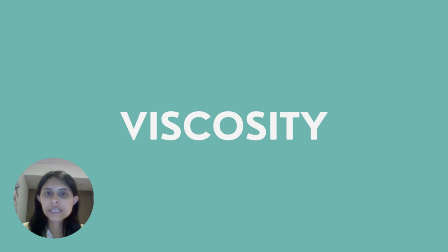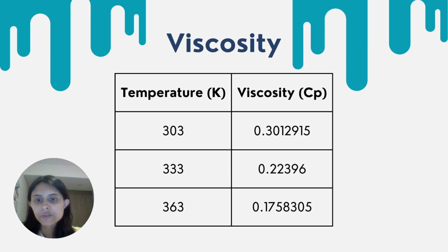After finishing all these steps, we will now see how this affects viscosity. Finally, in terms of viscosity, it is demonstrated that by increasing the temperature, the viscosity will decrease. This is mainly because in molecular terms, the Coulomb and van der Waals forces were weakened. The kinetic energy was increased and the potential energy decreased. This makes the movement of the molecules easier and as a result the viscosity will decrease. The values show that the viscosity is inversely proportional to temperature. This is evidenced by the fact that the highest temperature has the lowest viscosity registered.